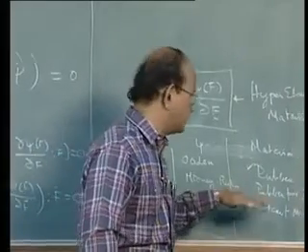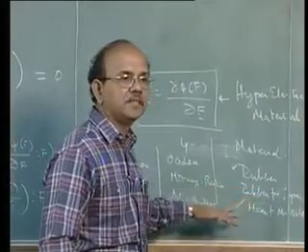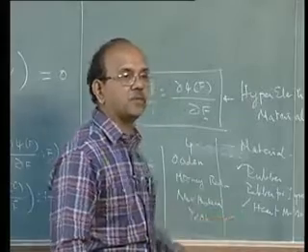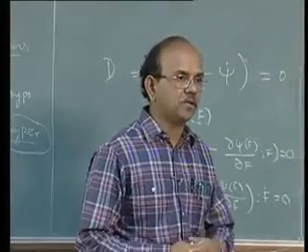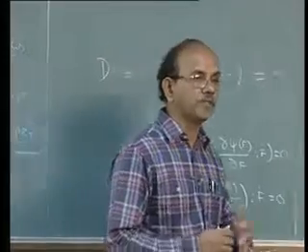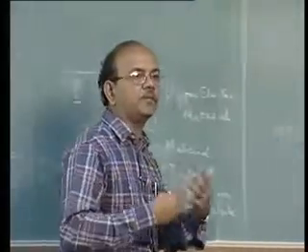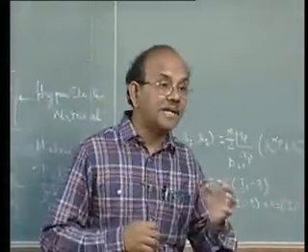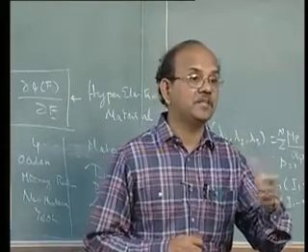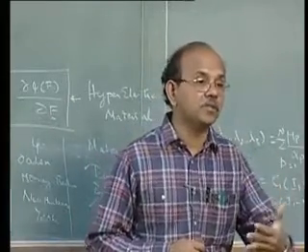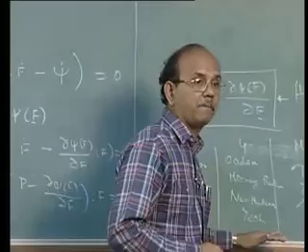Now there are reasons why, for example, rubber for tires is exceedingly well represented by Yeoh's model, because the shear modulus varies with deformation and is supposed to have a double peak. So that kind of mechanical behavior can be represented in a much better fashion using Yeoh's model.